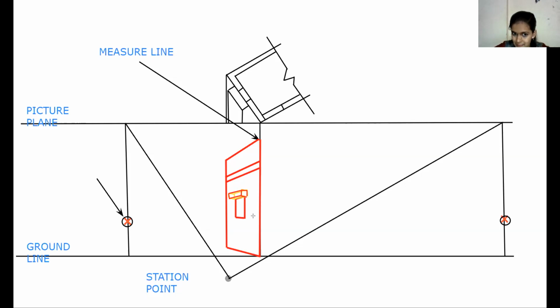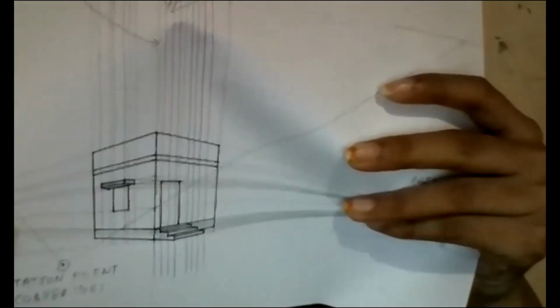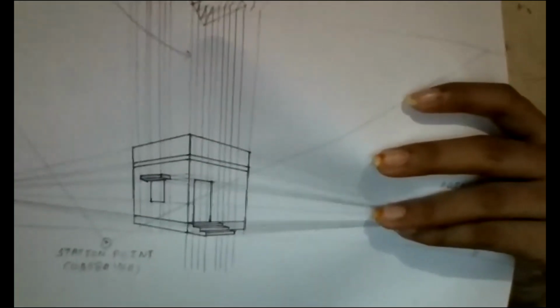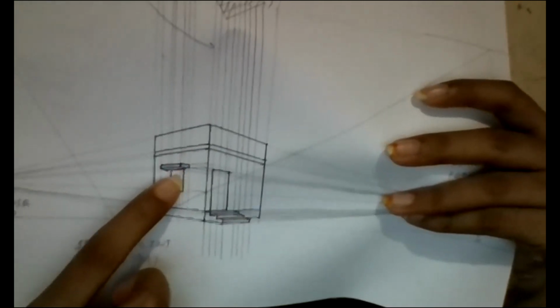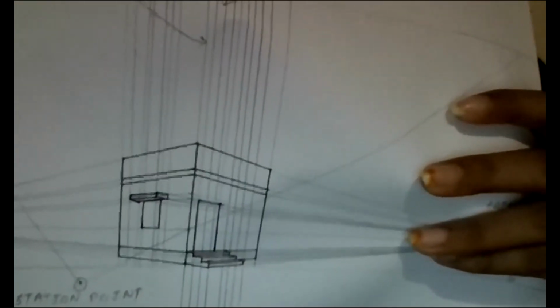Here it is, the sides, the bottom portion like this, and the line. Here it goes, a chhajja. Like this we can draw a chhajja. I'm showing you again what I have drawn on paper. So your chhajja will look like this. In this drawing, I have used the scale 1 centimeter equals 1 meter. The chhajja will appear like this, and you need to highlight it like this. You can see clearly how the chhajja will look.